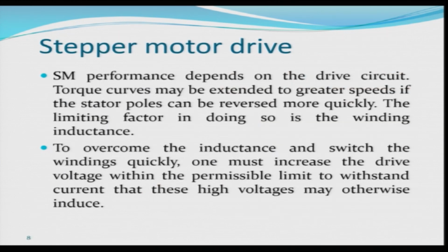Stepper motor performance depends on the drive circuit. Torque curves may be extended to greater speeds if the stator poles can be reversed more quickly. The limiting factor in doing so is the winding inductance.